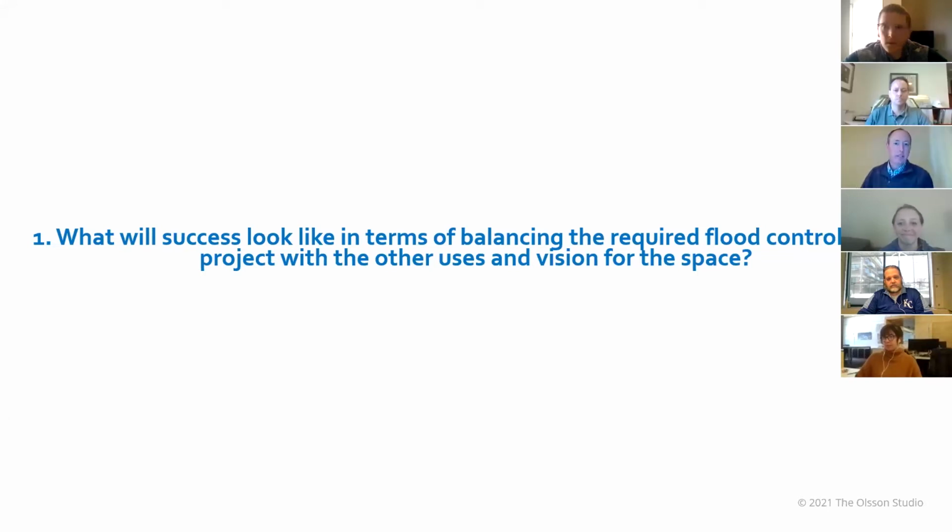Even the way it's worded, it uses the word balance or balancing, and I think that's what this is going to be: a balance. We have a goal to try to get the flood levels down below the finished floors of the buildings in the area, but we also don't want to design something that's not going to be able to accommodate the other goals for the project, including the other uses and elements that people want to see in the site.